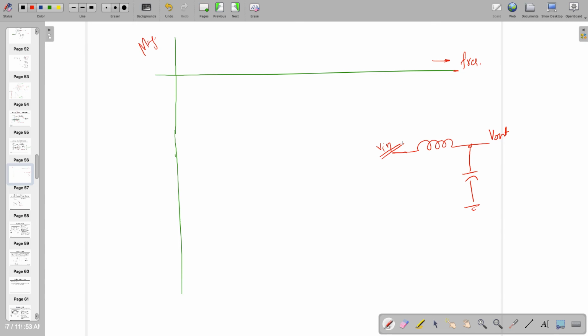The question is this one, not the resonance. Resonance condition has to be created. In RLC, how is it possible? You need to have negative resistance, right? You have to make an oscillator. You need a transistor somewhere to create that condition. Oscillations like Colpitts or relaxation oscillator, you are saying. Then it's possible, but you need one transistor. I'm talking only about an RLC circuit.